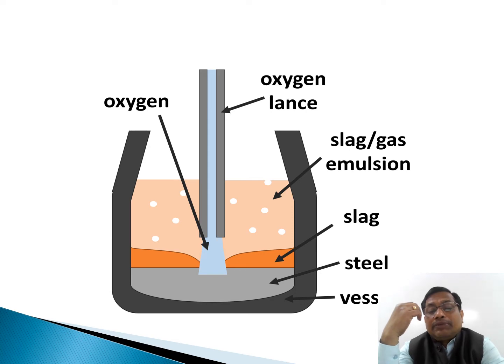After this, we tilt the converter. By tilting, we can first collect the slag in a ladle. After the collection of the slag, we collect the metal. The question arises how we do this; it is by vision, a manual operation. Using a double blue glass, we can see that slag comes out first from the converter.